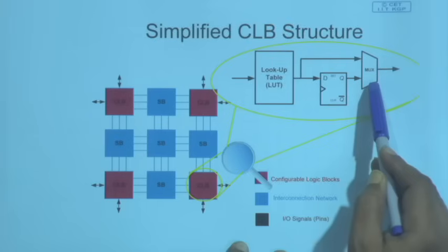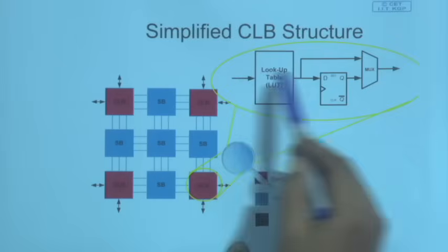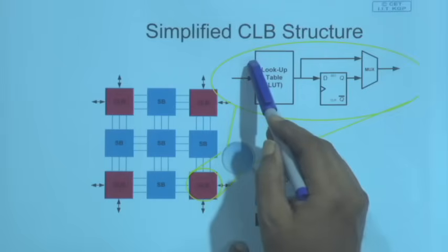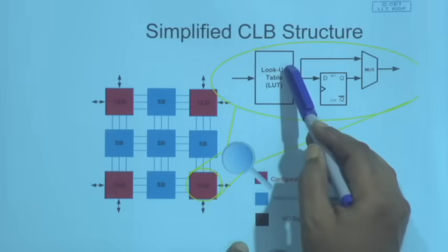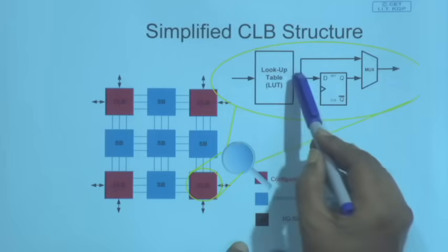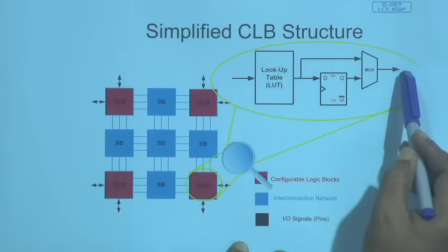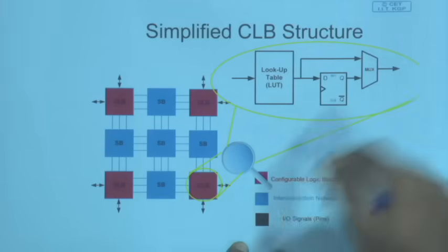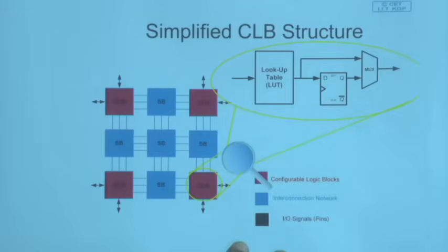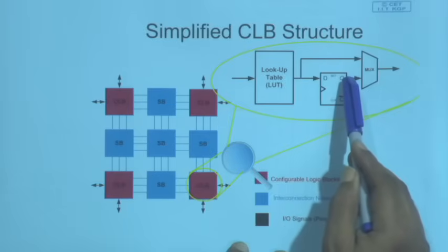Okay. So, whatever logic we implement, we can implement it through the lookup table. We explained that a couple of minutes back. The output of that lookup table I can directly take out, or I can take it at the next state. Therefore, I can put it at the D flip flop and it can be remembered in the D flip flop.